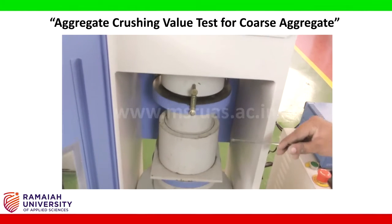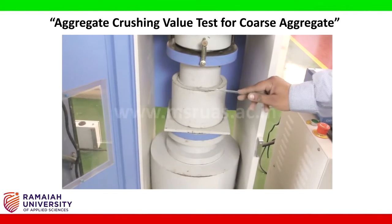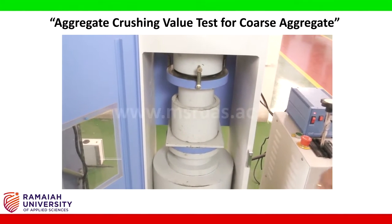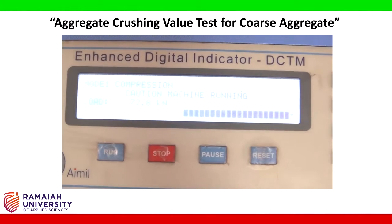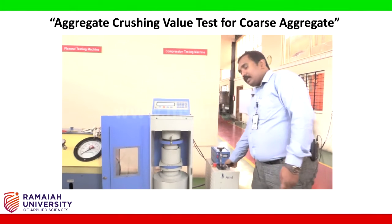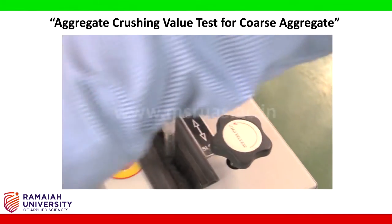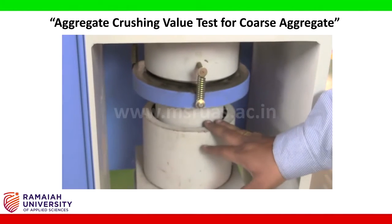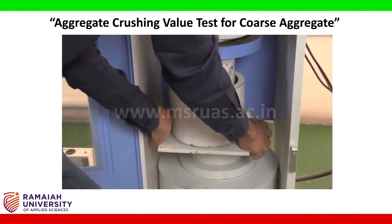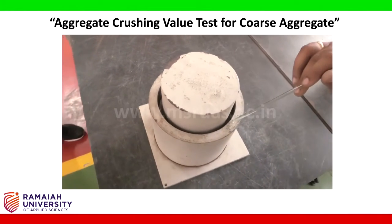When we are applying the load, you should make sure that there is an axial load acting on this complete setup. What is happening here? The aggregate inside the testing cylinder is compressed with the axial force. After applying 400 kilonewtons of load, we are going to release the load valve. Rotate in the anti-clockwise direction to release the load valve. Once it is releasing, you are going to observe the settlement of this plunger. We are going to remove this entire unit. And you observe there is crushing that happened in this aggregate system.